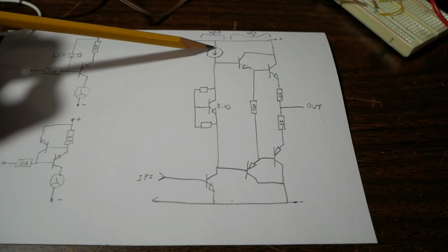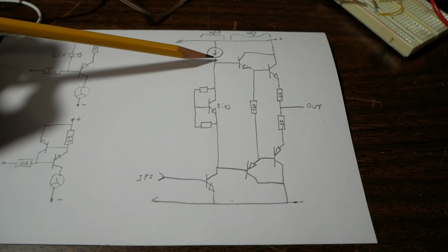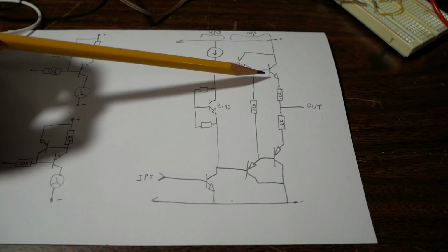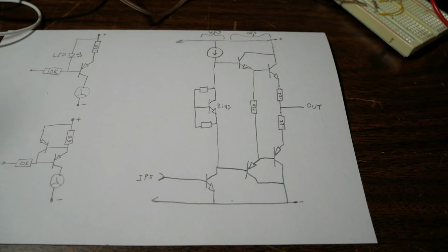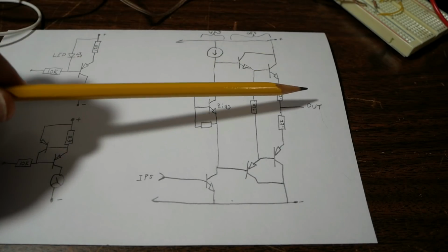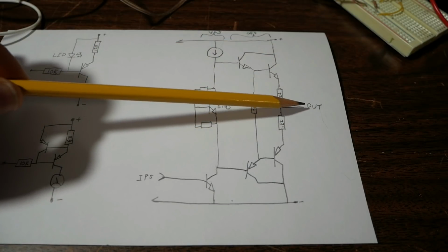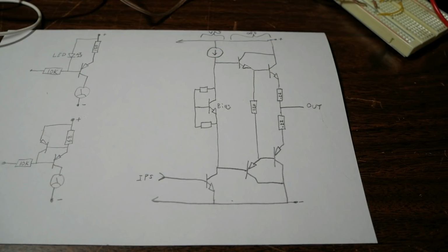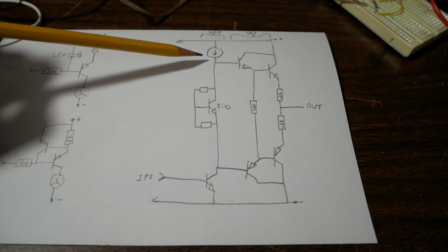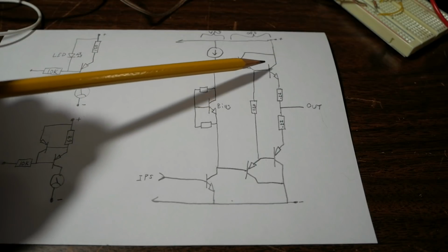And if this constant current source dropped out, in other words, stopped the regulating current, the current would fall, and now this part of the output stage wouldn't be able to deliver current where it really needs it at the peak of the waveform, when current's going to be high, at least with the resistive load, where it would deliver a lot of power. So you might end up with some asymmetry, some distortion. Of course, feedback would clean that up, but you would still clip early. You know, if there's not enough current here, the output stage cannot do its job.